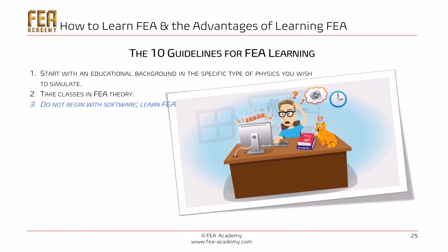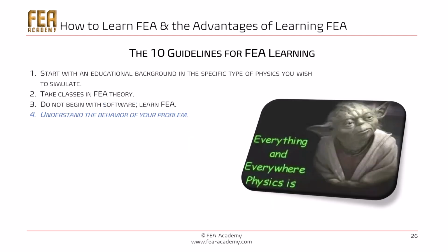Do not begin with software. Learn FEA. The software permits you to build and examine models, but it is dangerous to use it without understanding the underlying concept of modeling. Whatever software you use, the modeling techniques remain the same. Moreover, in the course of your career, you will probably change software packages several times. Understand the behavior of your model, okay? Or of your problem, I should say.